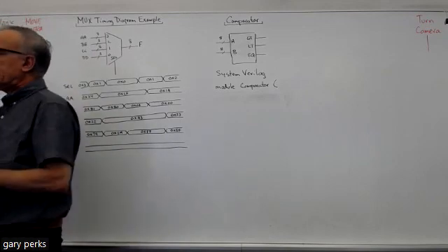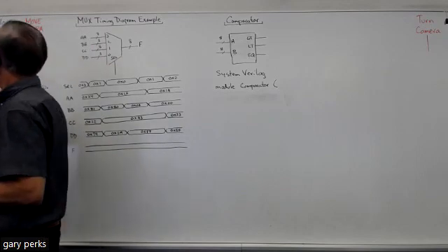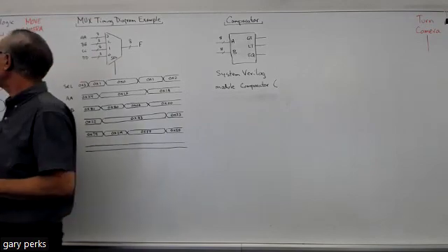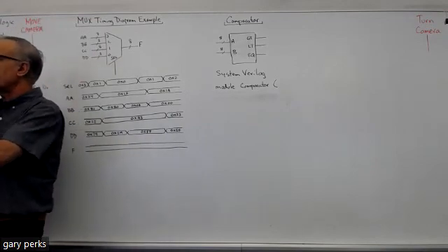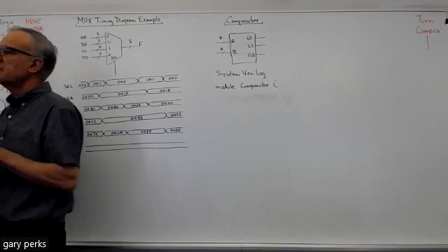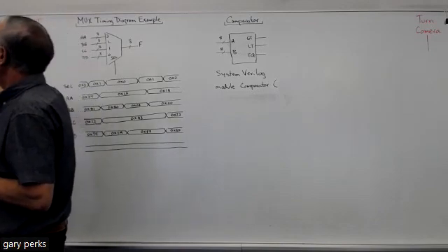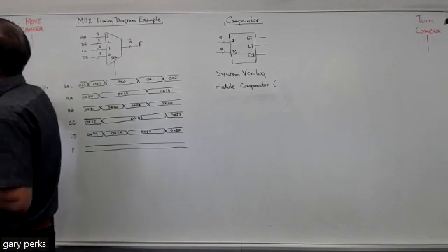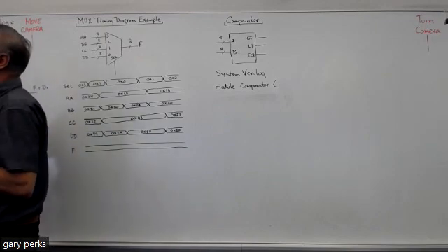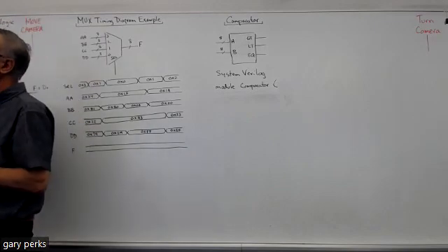So this 0 would be connecting that input to ground in a circuit, and a 1 is a positive voltage. If I made this bit a 1, that's like connecting it to plus 5 volts. So it doesn't have anything to do with the bit representation. Remember, if there's more than one bit, there'll be a slash with a number. So this would all be single bit, but the concept's the same no matter how many bits you have.